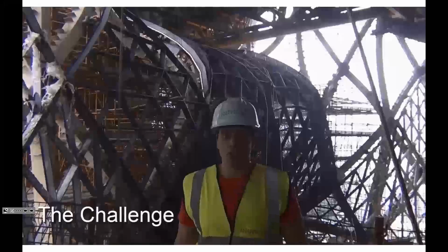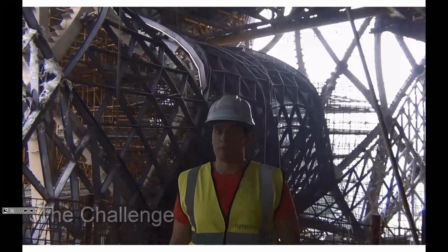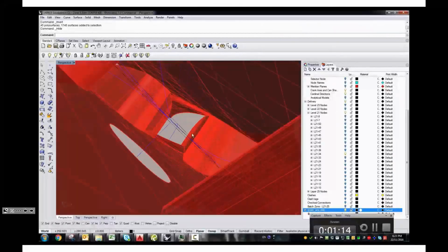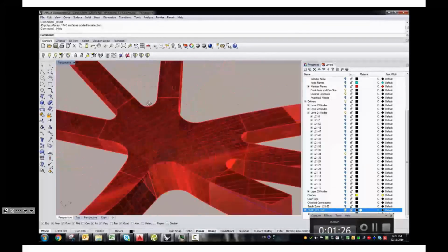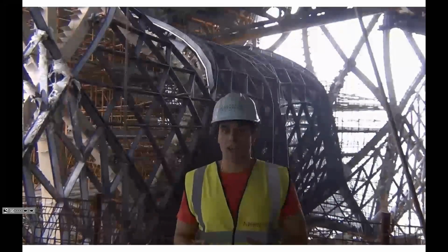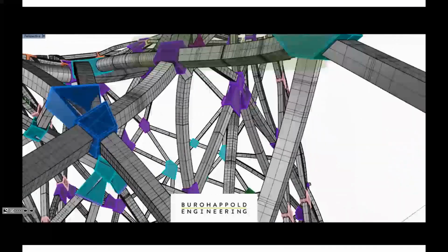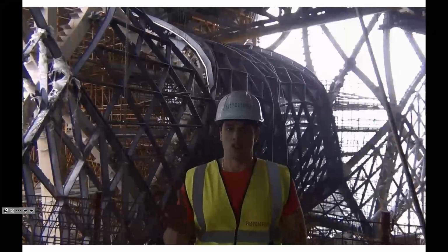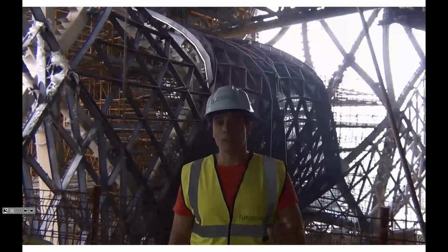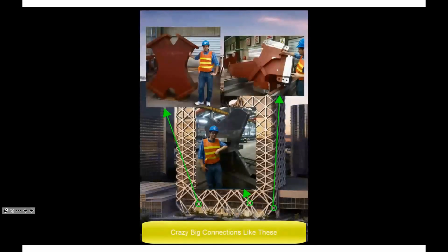So the design of the exoskeleton connections was something unlike anything that we normally see in structural engineering. There's 3 main reasons for that. First of all, we had massive architectural constraints in the form of a 3D polysurface coming from Zaha Hadid that we had to remain inside of. The second one is because of their bespoke nature, every single connection had to have its own way of getting documented. No one's ever seen connections like these before, so how on earth do you document these? But the topic of today's lesson is going to be, how did we do the engineering? The engineering challenges for this project were massive. And remember, on all of this, we had only 12 months to deliver detailed design information for over 2,500 exoskeleton connections.